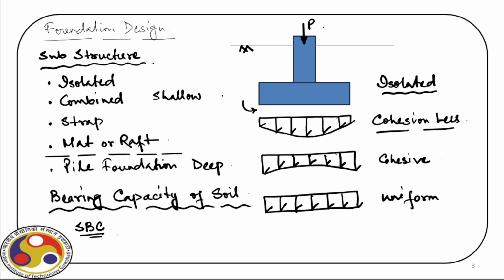Sometimes the settlement continues over a longer period, and we also have a long-term settlement of a particular site depending upon the type of soil we encounter. But when we design a structure, obviously we expect the structure not to settle over a prolonged period. Of course, there will be some settlement at the initial stage, and we design the foundation in such a way that this allowable settlement is actually taken care of within the design process.